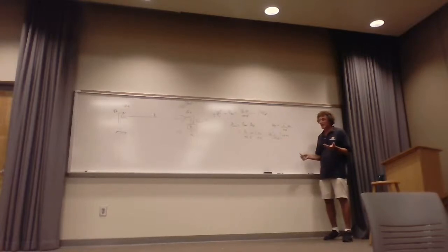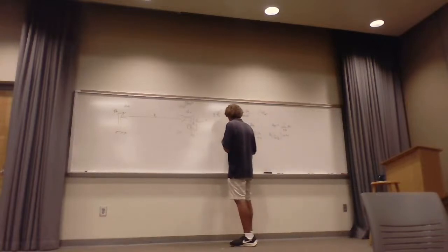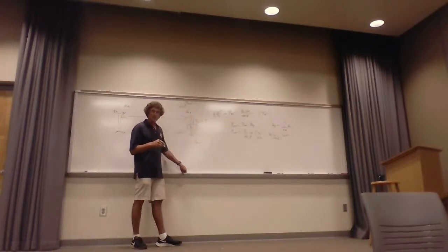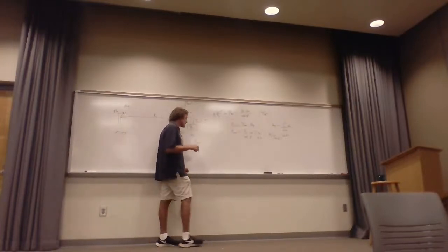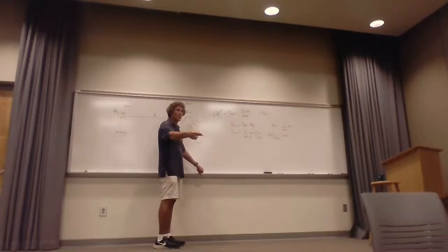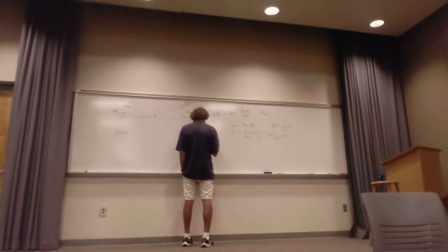Okay, that's P received. But remember, P received has to do with the maximum theoretical power. And that theoretical power, right, we found was equal to what? Do you remember this? Well, remember where I drew Z antenna and then I had Z load had to be the conjugate of that? So only the R mattered, so the real part of the antenna impedance. So that was equal to what?